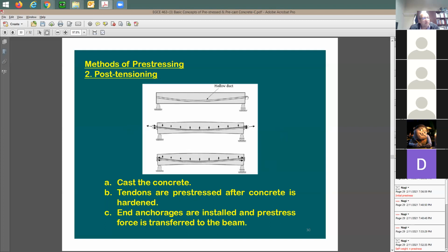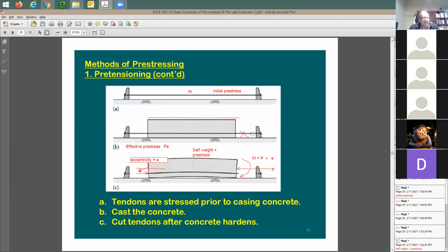And you see the way you usually do it, they drape it. We call this draping. It's not gonna be straight, most likely. If you do it on the side, it's gonna be like this. So here it's gonna be right at the mid-height, and here it's gonna be coming down. In the factory, they do it straight. Does it make sense to you guys? Why would they make it straight? Easier to control the depth.